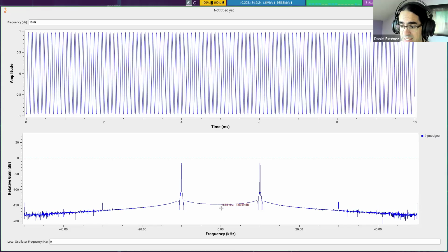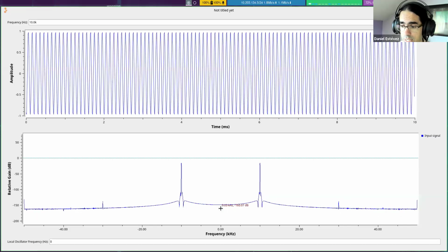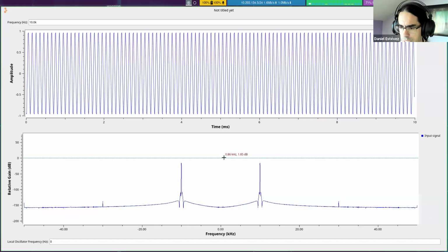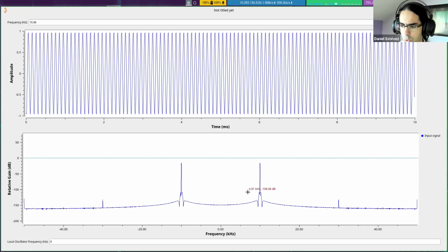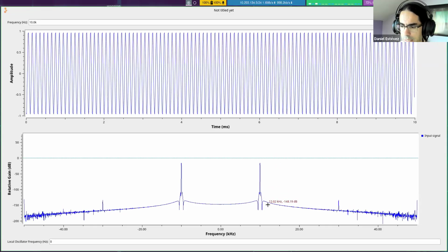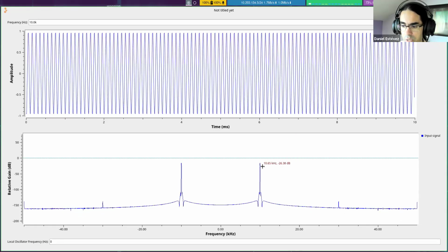You will have to bear with me that this is a useful operation to do in signal processing. It kind of centers things, right? If I want to work on the signal, it's better to put it at zero, which is like the center. Then, for example, if I want to filter the signal, I can use a low pass filter, which we will see in another week, which selects this part of the spectrum. It is way easier to work with low pass filters than with a band pass filter, which would be placed here. So you need to believe me that shifting things in frequency is a useful operation in signal processing.